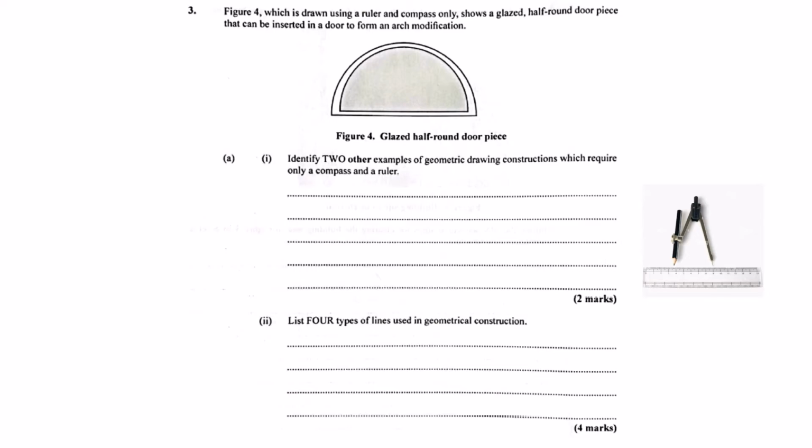What's that telling us? A center line has a specific pattern. Long dash, short dash, long dash, short dash. It repeats. This line marks the exact middle of circles or curves or anything symmetrical. It also acts as an axis of symmetry. So if you see a center line running through a circle on a plan, you know precisely where the very middle of that circle is meant to be. Gotcha. So these different line styles are basically a visual code, each telling us something specific.